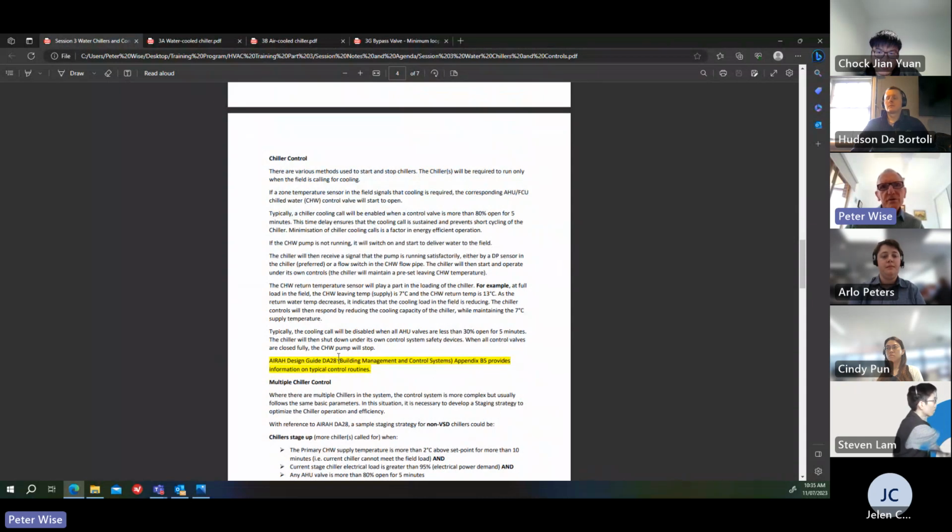There were 4 chillers initially. It's the same place now. It's got about 6 or 7, I think. So 4 pumps, 4 chill water pumps, all pumping into a common system, and then 3 bypasses on the return. So it was pretty complex at the time, but these days you can have variable speed pumps, variable flow chillers, and primary, secondary systems, variable primary systems, and we'll talk about that a bit more shortly.